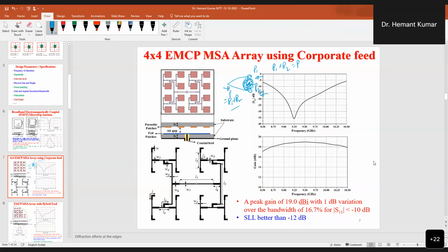In a Wilkinson power divider, we are using that resistor only so that we can use the power divider as a combiner also. But here there is no need to use it as a power combiner. We are only going to divide the power. We are not going to combine the power. So there is no need for it in this case. Okay, sir. Thank you, sir.